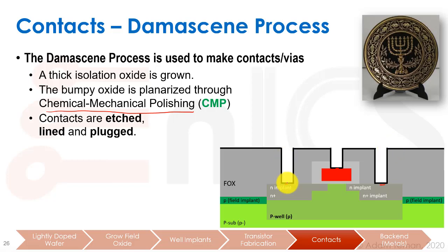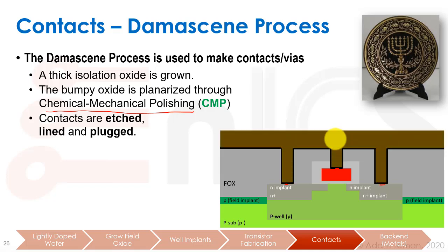One thing I want to point out is, we want to have a tunnel over here. We do not want to have this thing shorted to the sides, and right now we created this short, but we'll get rid of it in a second. Okay, the next thing we're going to do is pour our plug into there. Our plug is the material that we're going to make our contact out of, and it's usually tungsten.